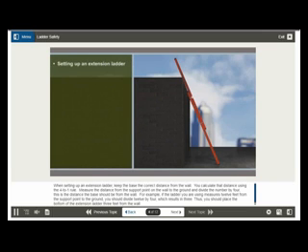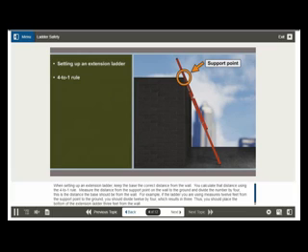When setting up an extension ladder, keep the base the correct distance from the wall. You calculate that distance using the 4-to-1 rule. Measure the distance from the support point on the wall to the ground and divide the number by 4. This is the distance the base should be from the wall. For example, if the ladder you are using measures 12 feet from the support point to the ground, you should divide 12 by 4, which results in 3. Thus, you should place the bottom of the extension ladder 3 feet from the wall.